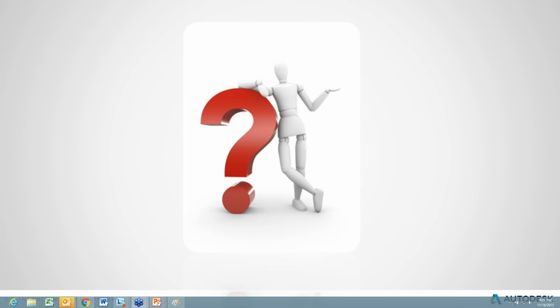All right, so let's move on to another question here. We constantly have an issue with installs of different Autodesk software due to .NET framework versions. Is there any way of preventing this? If the issue is that it's trying to install .NET and the install is failing on that, other than uninstalling or repairing .NET and seeing if that fixes the issue, one thing you can do is edit the setup.ini file, which is in the root of the install files, the same place where you'd run setup.exe.